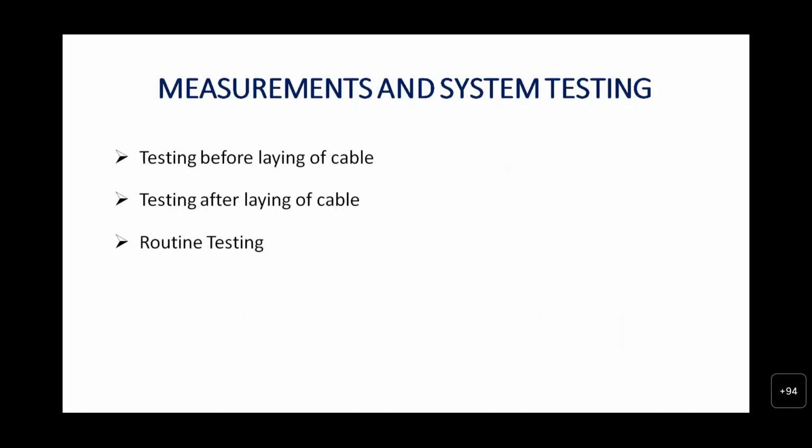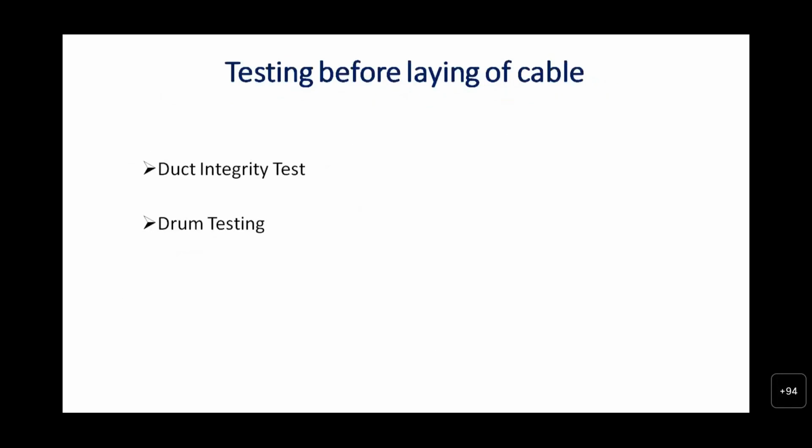Similarly, here, unlike in quad cable, OFC also is to be tested before laying the cable, testing after the cable is laid, and routine tests are to be conducted. And as all of us know, the OFC is laid inside the duct, and the duct integrity test also is to be conducted, and the drum test also is to be conducted.